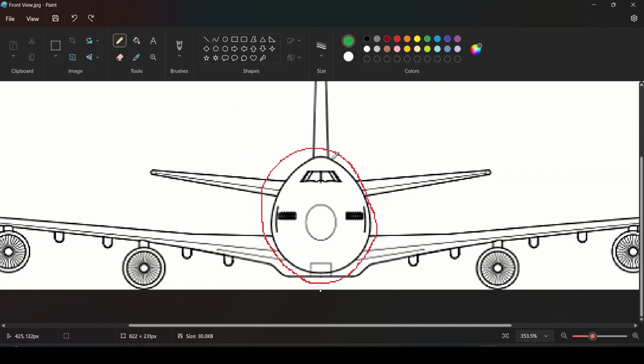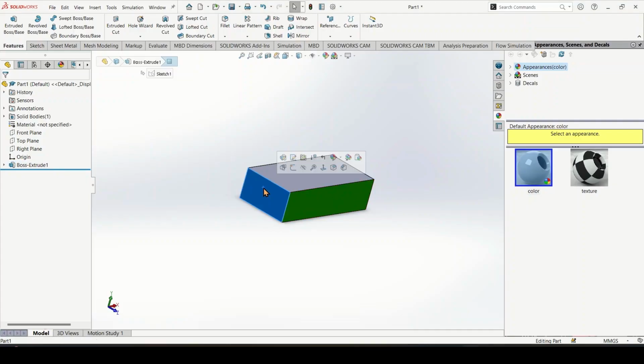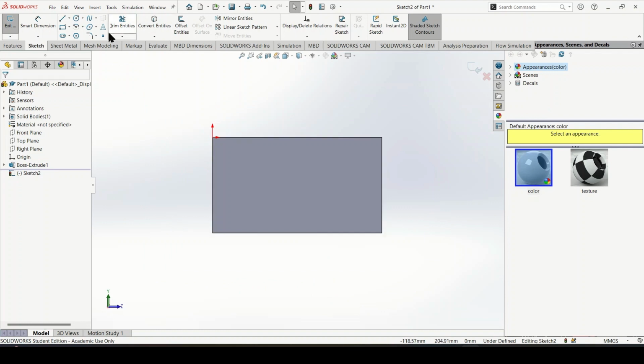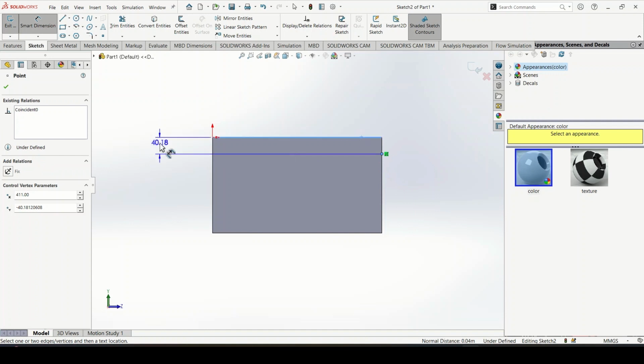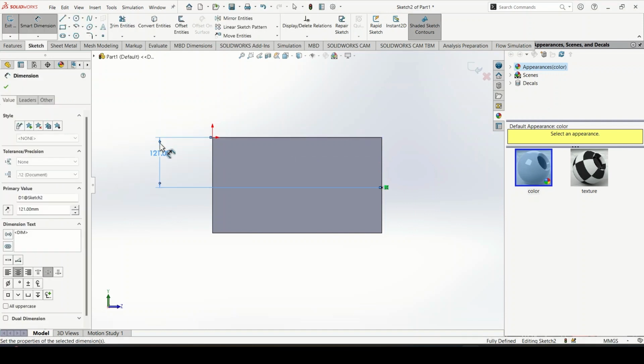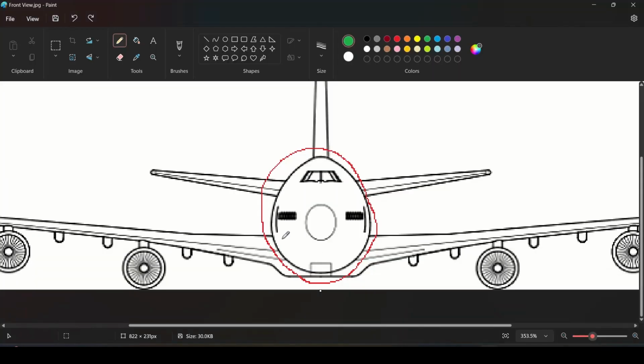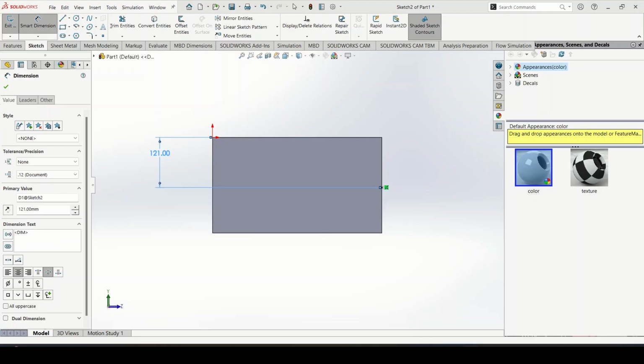So we can look down at the coordinates in the bottom left and see that it starts at a height around 121 pixels down. Start a sketch on this plane. Create a point on this line here. And going to this corner over here, we can see it is at 369, 176.